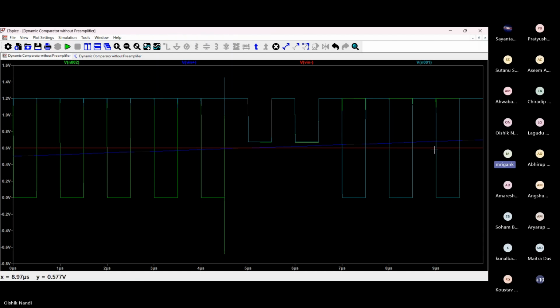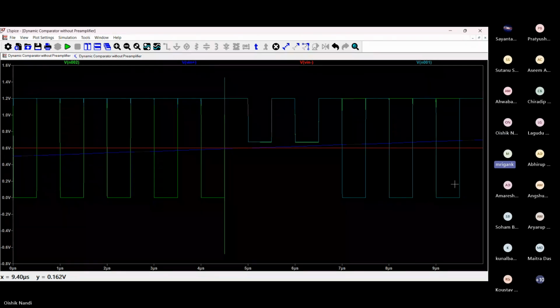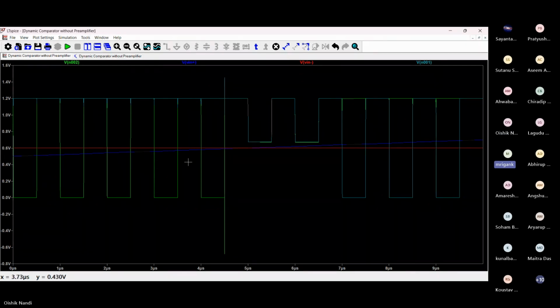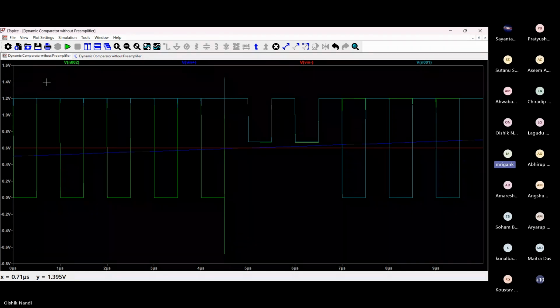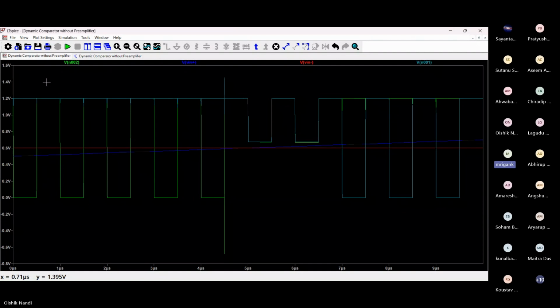It will switch. Another thing that we have not discussed is the inclusion of noise. In commercial simulators like Cadence, we have the option of including transient noise. In that case, whatever thermal noise, 1/f noise, etc., comes from the device, it includes that in the transient simulation. That will also affect your resolution. If the noise of the devices is pretty bad, then your resolution will be affected by that noise, because the noise itself is several hundred microvolts.